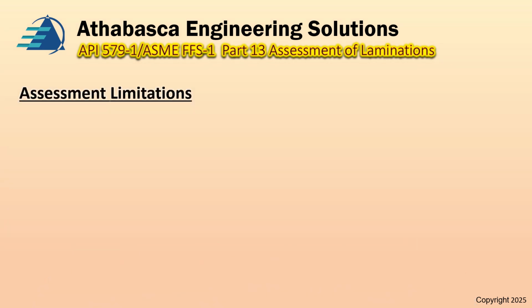Now the assessment limitations that API lists for doing the fitness for service Part 13 assessments. First of all, the assessment is designed for pressurized components with laminations. It's not been designed for structural laminations, and that's very important to consider.